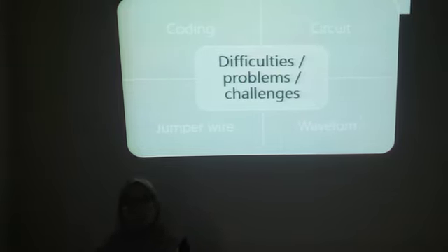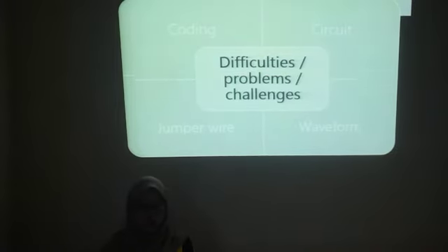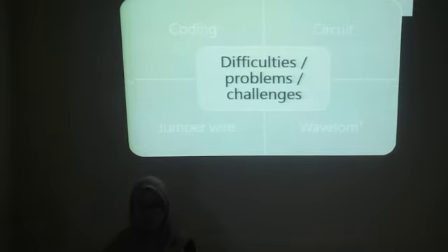Next is the jumper wire. For the jumper wire, we advise making your own jumper wire, because the jumper wires at the electronic shop have some problems. Once the jumper wire is in a vibrating situation, it can break, so your connection will be interrupted.